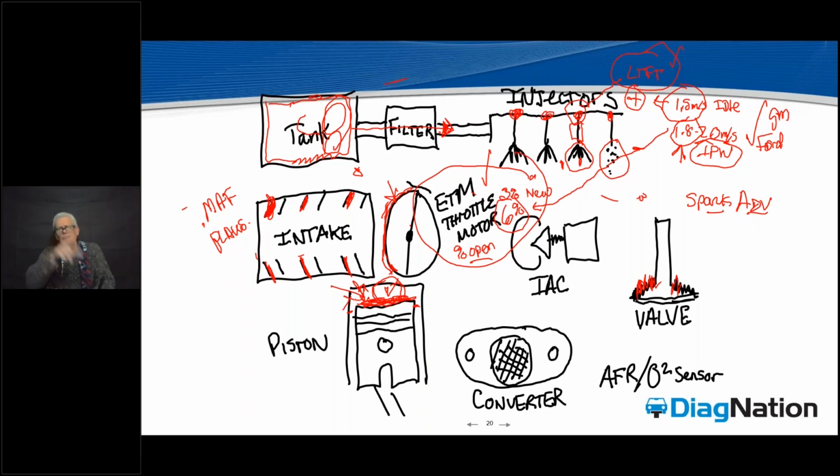And finally, that soot deposit, okay? The mixture of oil burning and soot is going to begin to impact carbon into the substrate of the converter. This is a very big argument for a tank additive like a 44K or an ATS tank additive or a WINS or whatever system you use. Very, very big argument for that. The big reason is the more oil that is going across that converter, the more poisoned it gets and the more chance we have of the P0420 and P0430.